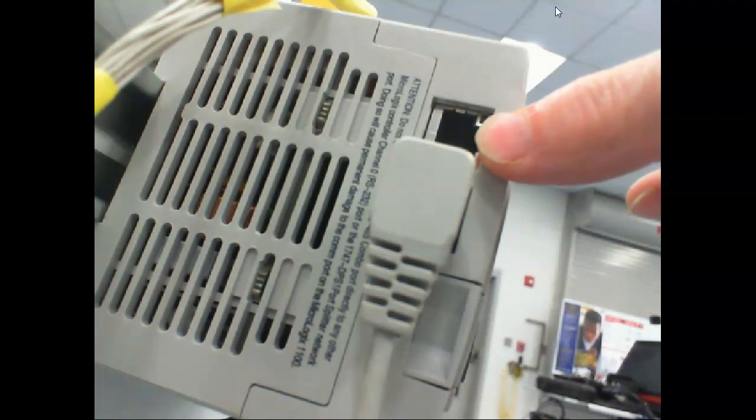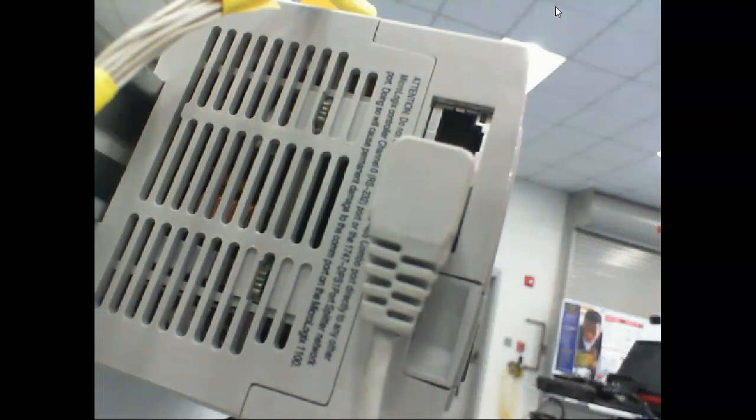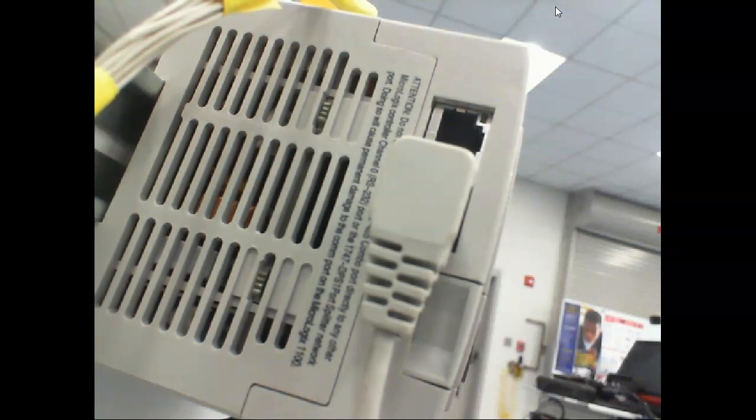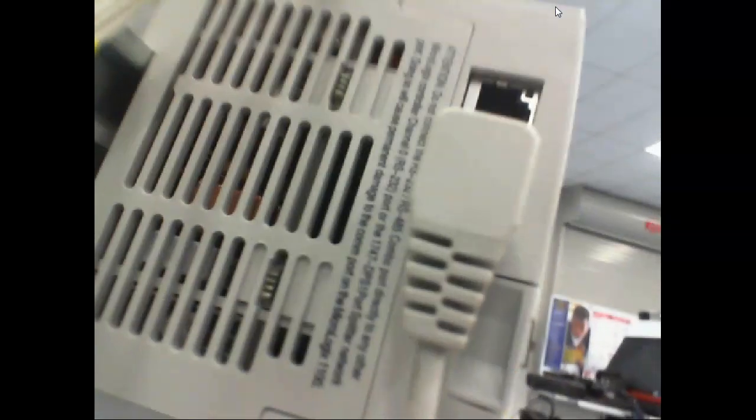So this is for Ethernet IP. This is for an interface called DH485, which we'll talk about more. And this is the one I'm using because it's peer-to-peer, which means it's designed to hook from a computer into the PLC or from a computer to another computer without having 15 or 16 or 300 computers communicating at the same time.